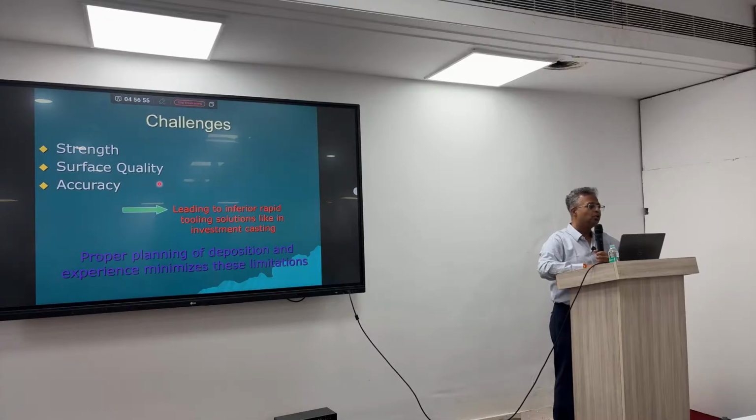And accuracy is also low because the deposition takes place in an uncontrolled manner; there is a free flow. In compression molding, there is a constricted or limited volume, the limits are known, and you are pouring and pushing the material into it, so the accuracy is very high.